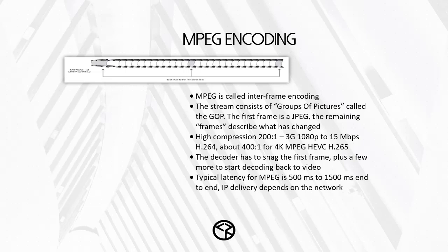The problem that MPEG over IP has typically had is that a lot of losses and time delays are taken up by the network. So you're not at 500 milliseconds. You're actually at, in some locations, an 8-second delay, which I would call a poorly done system, but still, it can be a much longer delay, where RF is instantaneous, and that's kind of the difference between how MPEG is used between RF and IP.